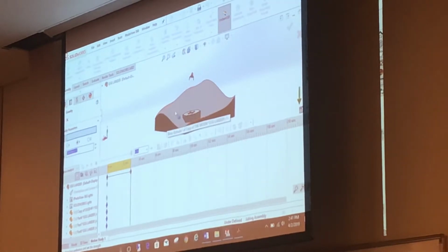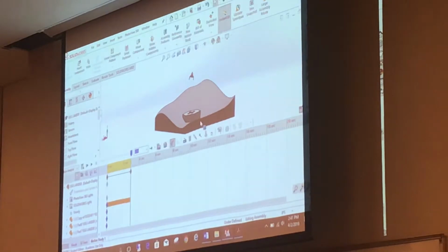So if this represents the surface of the moon, if I remember right, I think the moon's gravity is about 1/6 the gravity of Earth, right? Does that sound about right? Yes. Okay, so the value that we're going to use is 1.62 meters per second squared. Okay, so I'm going to type that value in with its units, and when I hit enter, SolidWorks goes ahead and converts that to the proper units for our IPS current unit system. Okay, so make a note of that. 1.62 meter per second squared is the value of gravity that you'll use. And I'm going to click the green check mark.